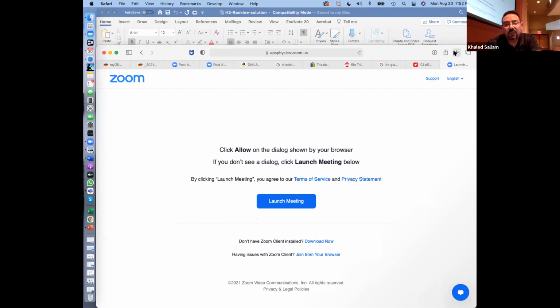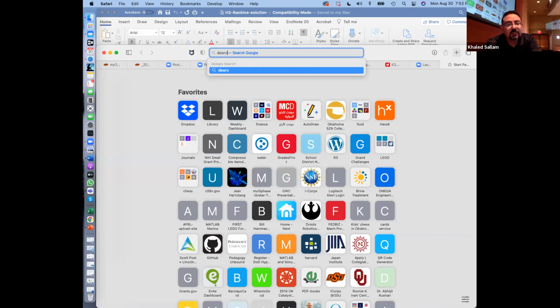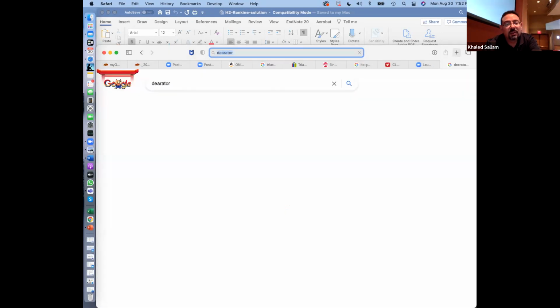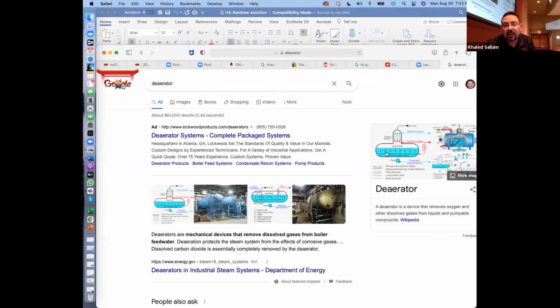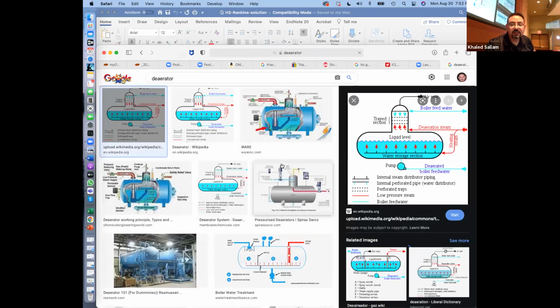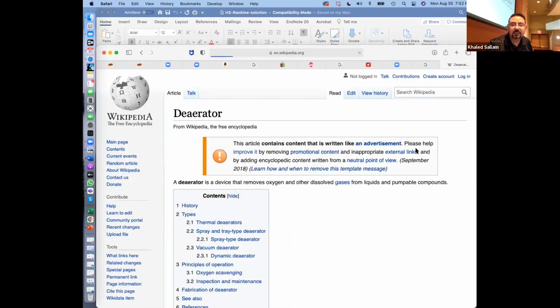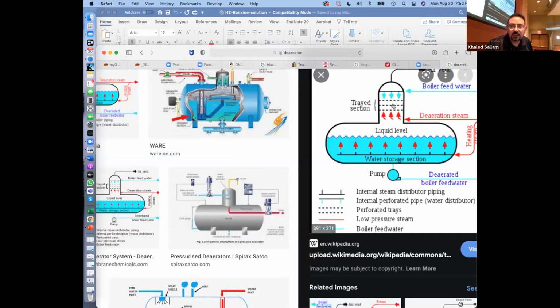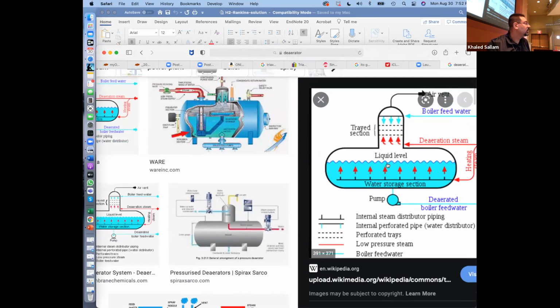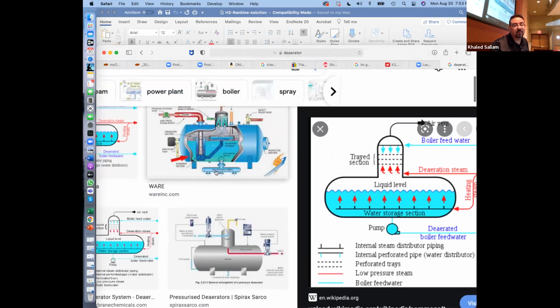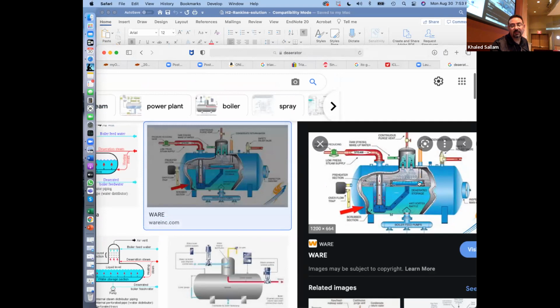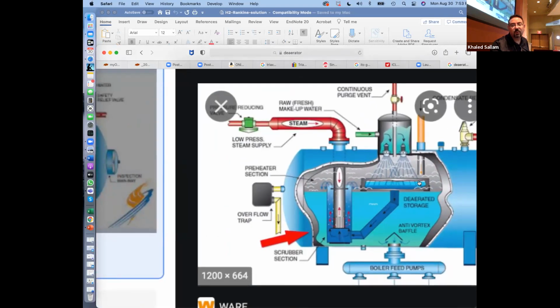If you look at the picture of a deaerator, you'll find it's really done so that you can release the air. Yes, it's heating, but it's really for this. It's really so that the air can leave from the outside. One big tank, this is the place where the water and the steam mix together. Okay, see how it looks? Big tank with the water sprayed in the steam.